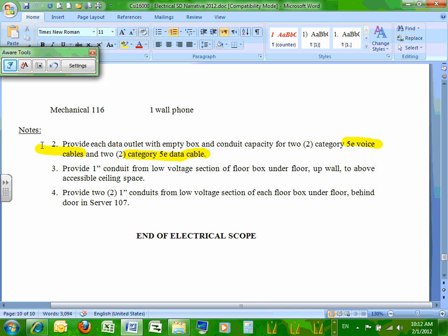That's as simple as a keynote explaining to the contractor that's bidding the project that he should put a J-hook every 5 feet to support data cables, or tie wrap it to the joists above, or just something to get it supported.